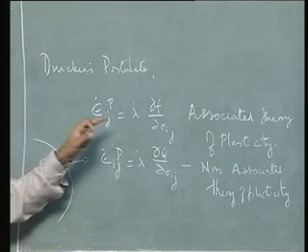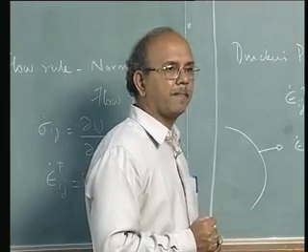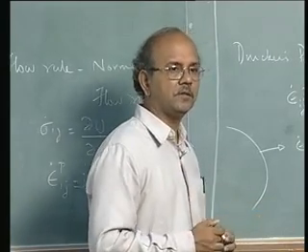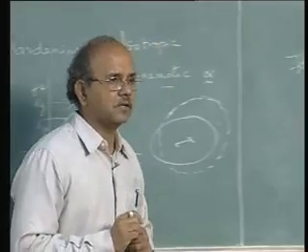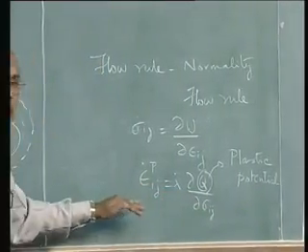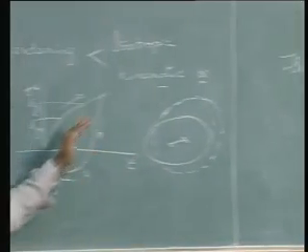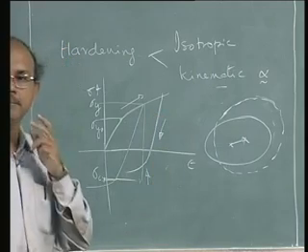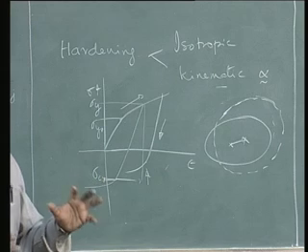Now, let us determine what is ∂f/∂σij, say for example for the Mises yield criterion. Let us see how we determine ∂f/∂σij. But before that, we have to sort out a small confusion which may arise when I link up this ε̇ij^p or δεij^p and the plastic strain which I have to use to model isotropic hardening. Is that clear? There is a small confusion.